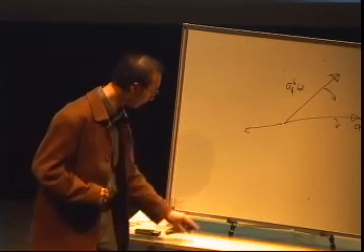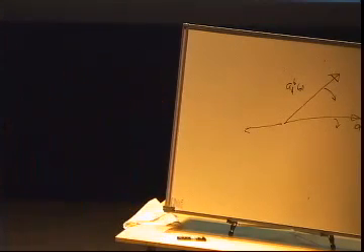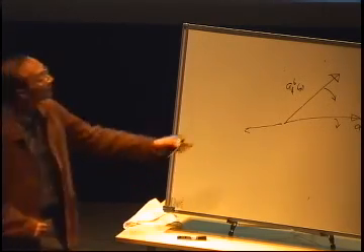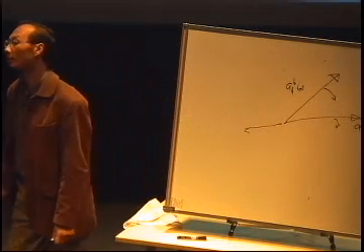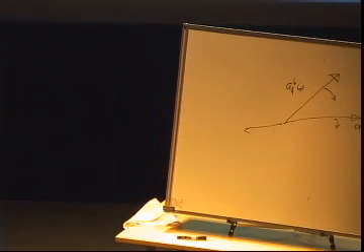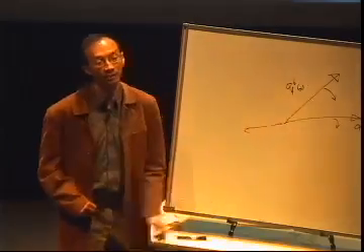And the variation is coming from Doppler spread. So the important thing about how fast the variation is not the absolute Doppler shifts, but the spread of the Doppler shifts. So the spread of the Doppler shifts is essentially the range of the fastest and the highest and the lowest Doppler shifts.